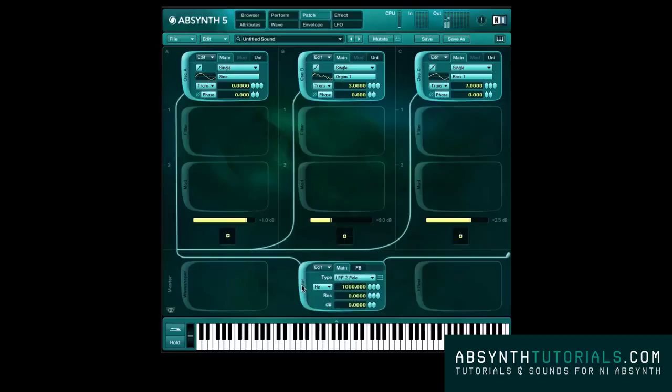The resonance setting underneath the frequency value gives your sound a little more presence. To test it, I'll set it to a low value like 0.3. At the bottom, there is a damping control option. This will let you compensate the outcoming filter result for the attenuation being caused by the filter.